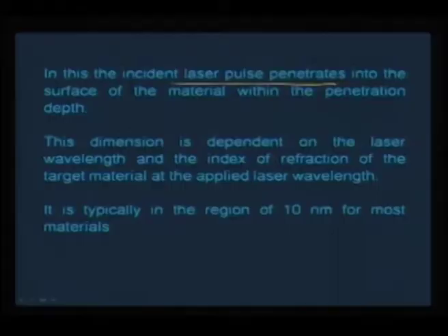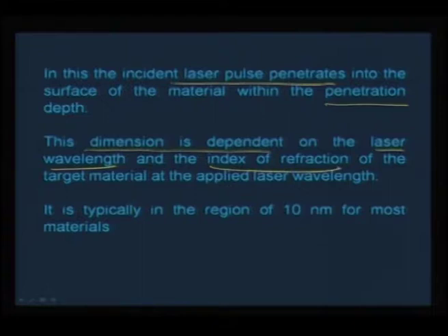But if the penetration depth is quite deep, then you will get almost all the species that is required out from the surface of the target. So this dimension is actually dependent. The dimension, meaning the penetration depth, is dependent on the laser wavelength and the index of refraction of the target material at the applied laser wavelength.